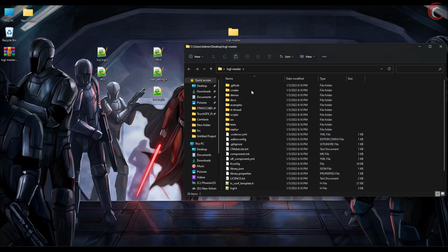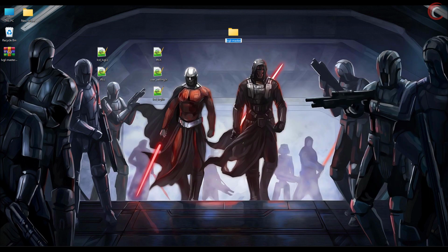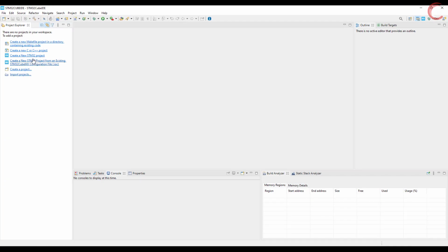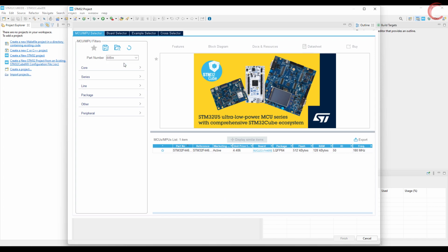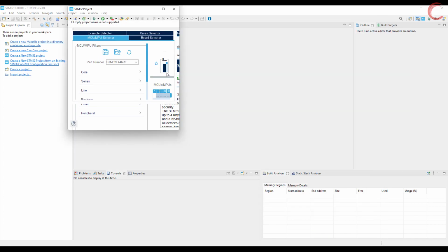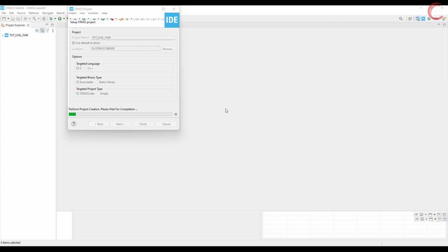Here is the extracted folder. We don't need everything in it, like demos is not needed, along with that Zephyr folder. I will keep it though, since I am not going to include them anyway. Rename this folder to LVGL. Let's keep that aside, open the Cube IDE and create a new project. I am using F446RE controller. Give some name to the project, and click Finish.